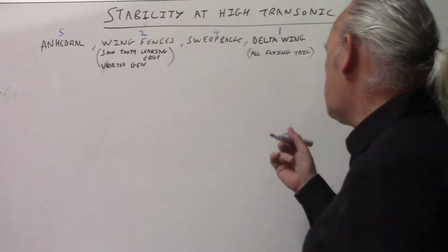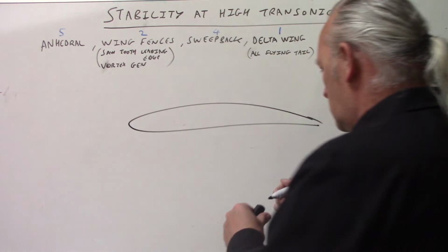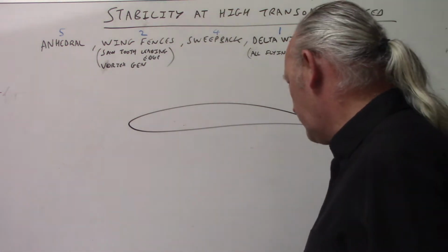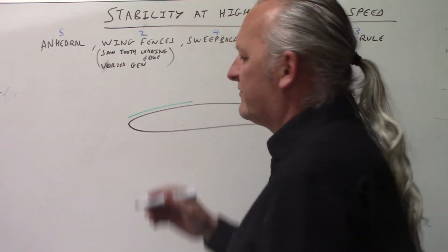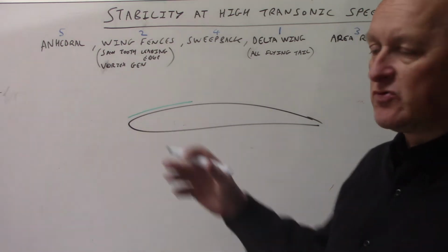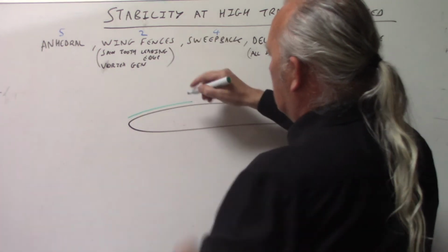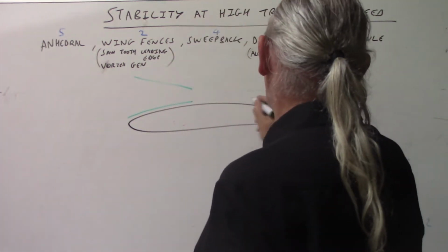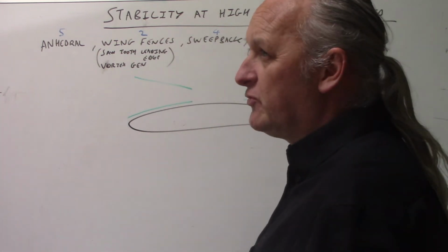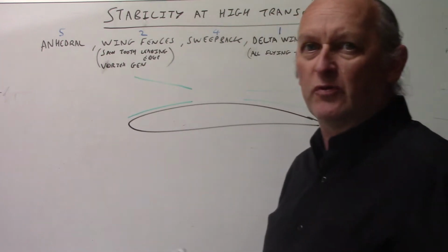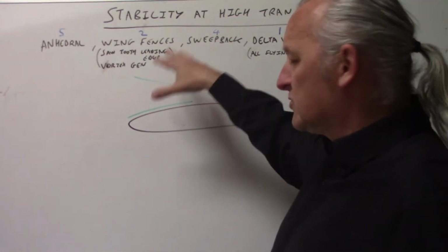Sorry. Okay, you've got your wing, you've got your standard aerofoil sitting like that. And then we'll have some airflow over it. That air will be accelerated at the first part of it, over that bump, over that camber, the camber on the top surface of the wing. You've got the atmospheric pressure pressing down and you've got airflow, and on a wing you have a convergent and a divergent duct. The other half of the Venturi tube is kind of there, but the Venturi effect is caused by the atmospheric pressure pressing on all sides of the wing, on the bottom as well as the top.